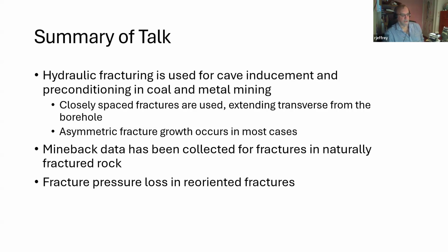Aspects of using fracturing around mines that we can take advantage of are that we can usually put in extra monitoring, and we can sometimes carry out mine back operations to map the fracture as placed, or at least the propped extent of the fracture, and see the details of how it grew through the rock mass.